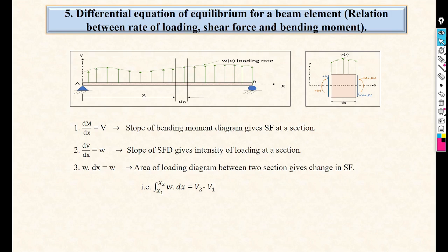So, when we consider the integral of w with respect to x, the area of the loading diagram between two sections gives the change in shear force. If we take the area of this portion, between that area we can calculate the shear force.